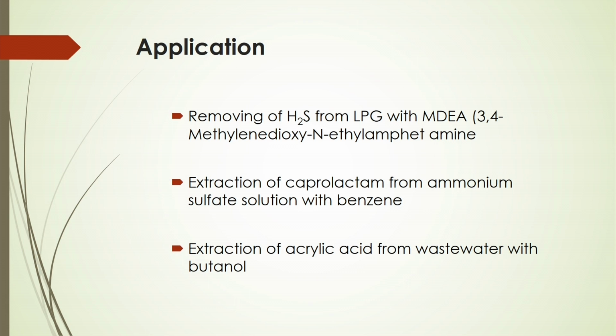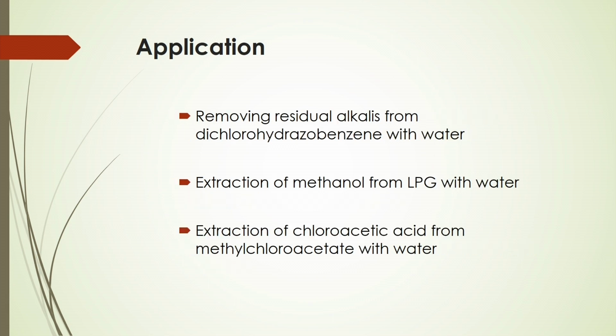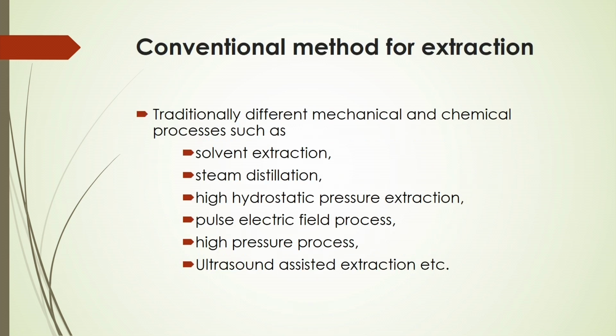Even other applications like removing hydrogen sulfide from LPG with MDEA, and also extraction of caprolactam from ammonium sulphate solution with benzene, extraction of acrylic acid from wastewater with butanol, removing the residual alkalis from dichlorohydrazobenzene with water, extraction of methanol from LPG with water, extraction of chloroacetic acid from methyl chloroacetate with water. This type of application is there for the extraction process.